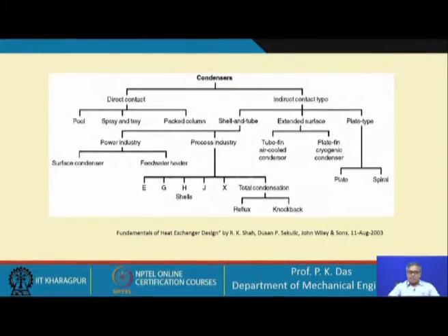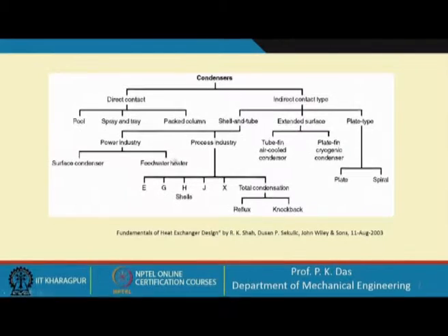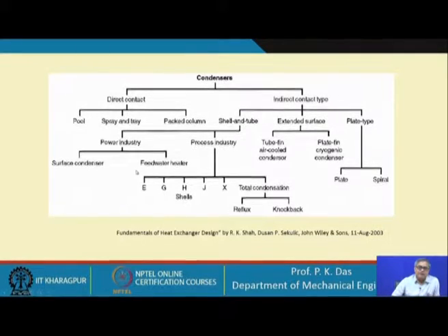This can be done by different methods. It can be done by the flue gas, but it can also be done with the help of steam taken from the turbine, and these kinds of heaters are called feed water heaters. So, in feed water heaters we are taking steam, that steam is condensing and heating the feed water.